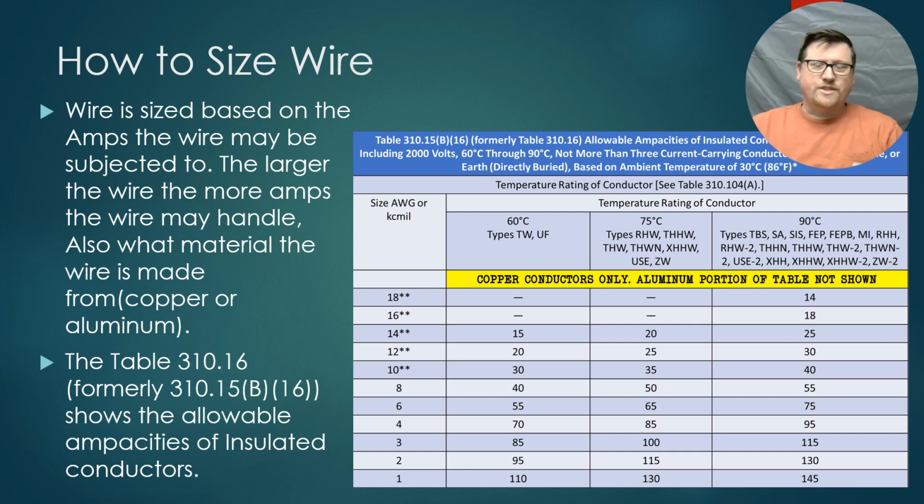All right, so if we're going to size a wire, the first thing we've got to know is how many amps does the thing have that we're trying to provide power for, right? That's what's going to be the basis of our wire size.